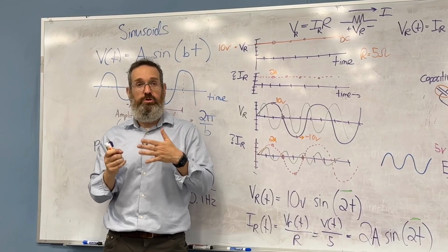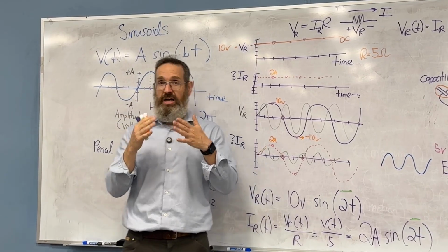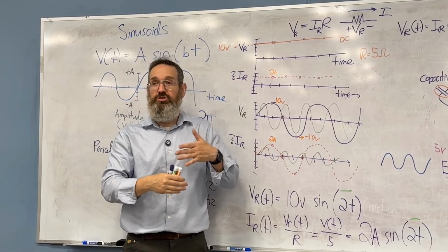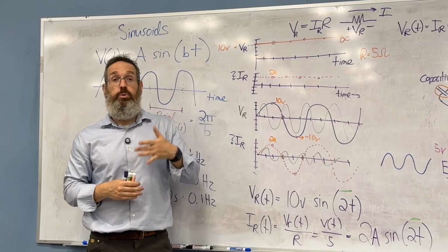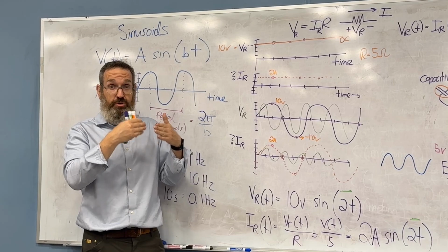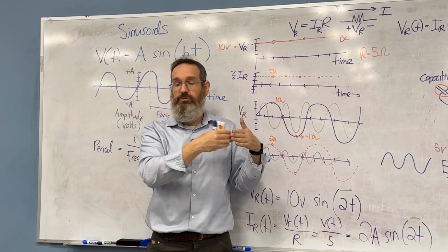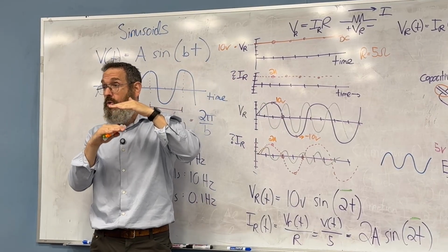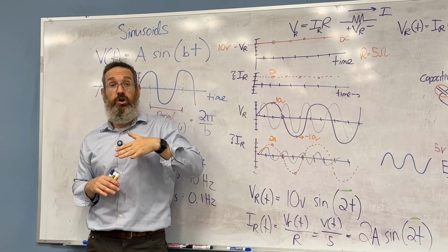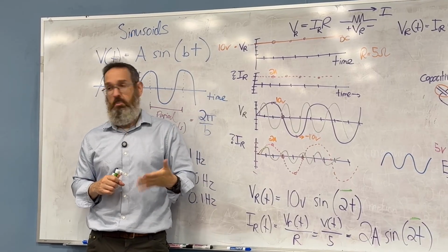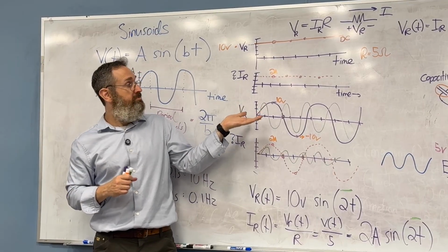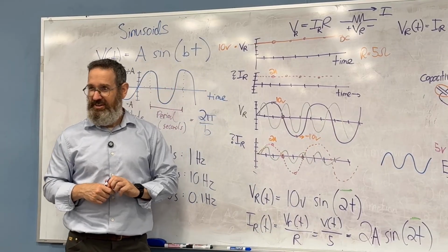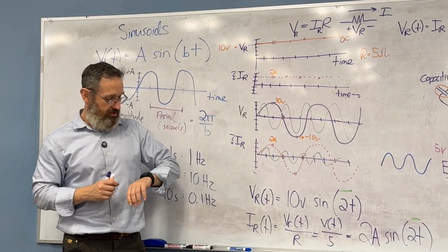Sinusoidal steady state analysis means a sinusoid comes in, and the thing that has to come out on the other end is also a sinusoid, part 1. Part 2 is the frequency of the thing that you bring in is the frequency of the thing that comes out. You don't have control over it. The only thing you can control is whether it gets squashed or expanded. And they call it sinusoidal steady state analysis because it's sinusoids, and things are kind of going steady here, and we're analyzing it. Got it? Except, you know, we could have done it a lot quicker, of course.